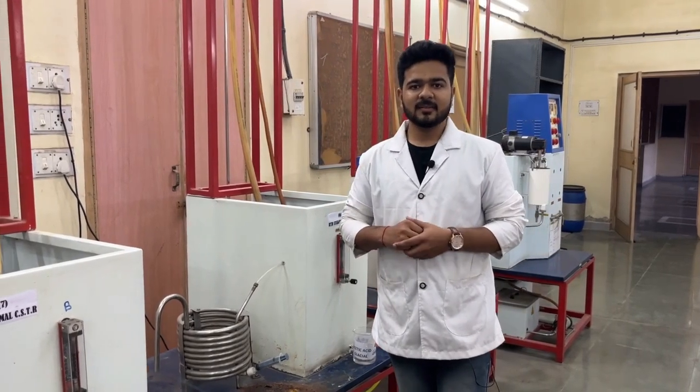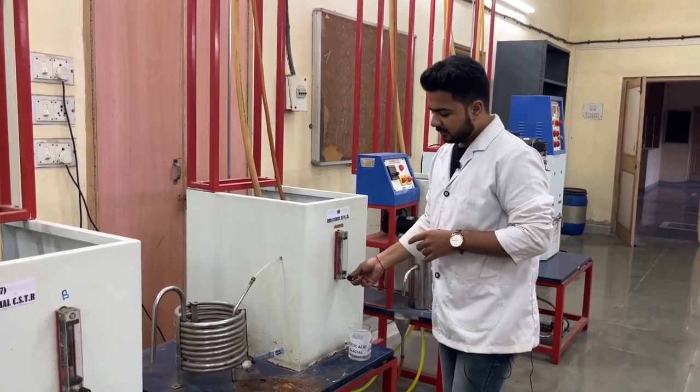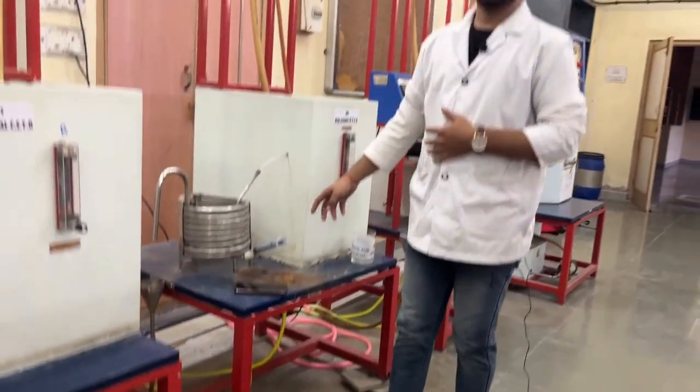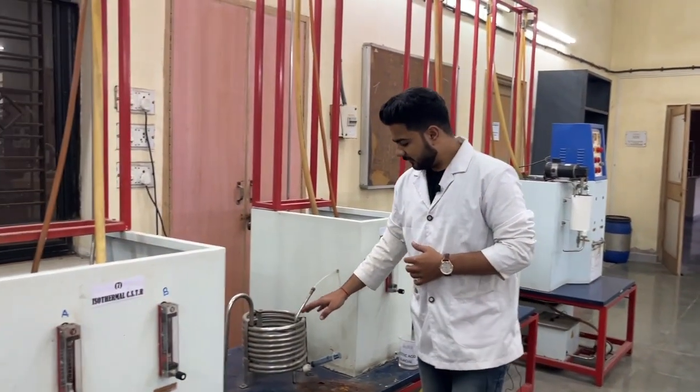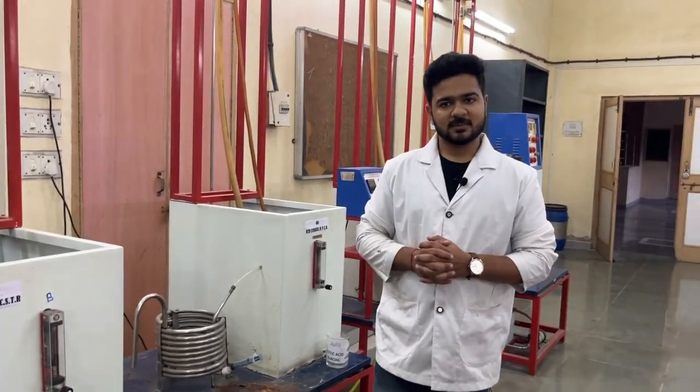After the 15 readings are done, we will turn off our flow rate to 0 and we will turn on the drain valve of the reactor and let the PFR drain. While the PFR is being drained, we will perform our titration.